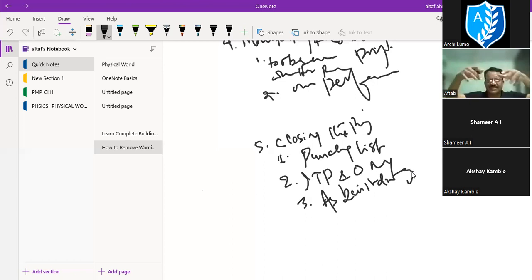The real measurement of each and everything, and the real actual built drawing as per the site condition, whatever we have built: the whole drawing, section, elevation, plan, everything is produced. Those changes are attached with certification and stamping from both sides, contractor and consultant or client, and that becomes an approved as-built drawing, which has to be submitted to the client along with the IFC or GFC.